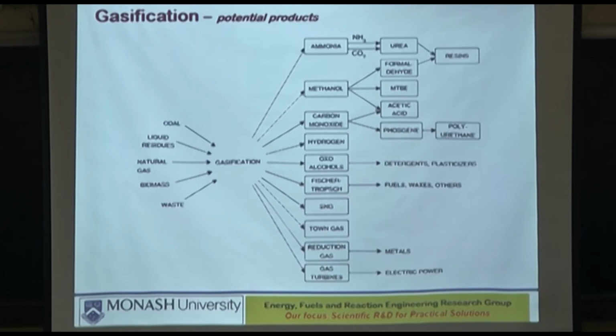Fortunately though, the methane is not much more than 3 or 4% of the total, volumetrically, in the total gas coming out of the gasifier. Unless you are running the gasifier at a very high pressure, where extra methane can be generated from carbon and hydrogen reaction, but that doesn't happen at all below 25 bar. You will require 30 bar, 50 bar, upwards of that. So extra methane will never be generated. Methane will be coming mainly from the pyrolysis source.